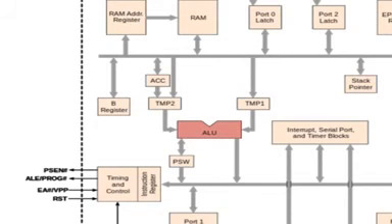So the A register must be used as the destination for all the arithmetic operations. And for logical operations, it can be used as source or destination, anything. Next, there are some specific operations like clear, complement, rotate and swap. For these we must use the A register only. Apart from A, you can't take other registers, it is invalid and won't accept other registers.